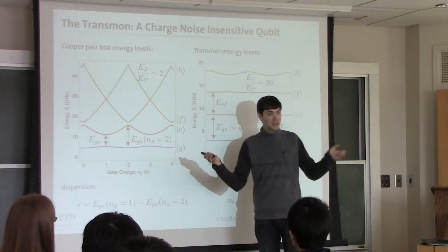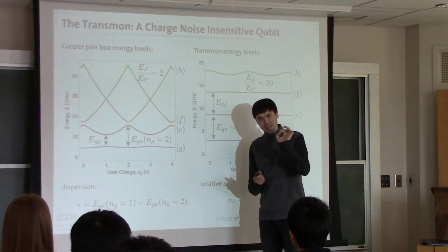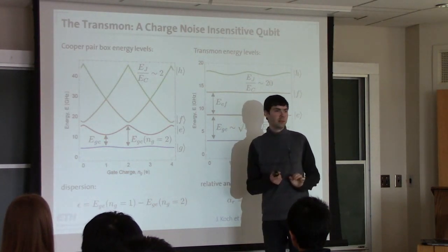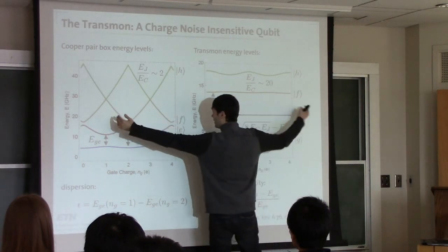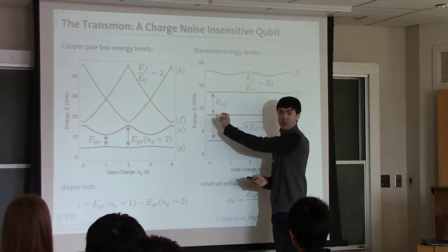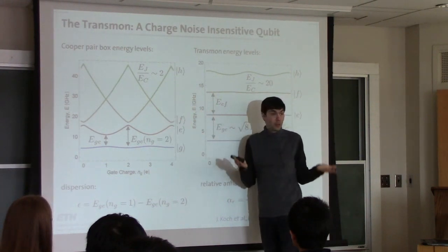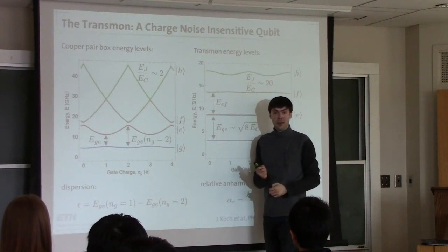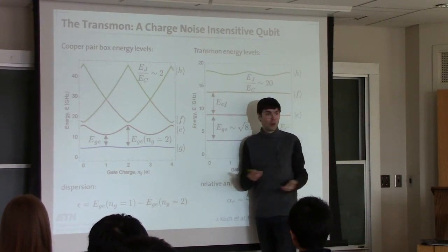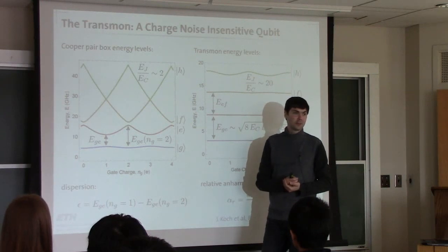It's a big capacitor with a tiny, tiny Josephson junction element that makes it slightly anharmonic. This is what it is physically. It's a capacitor this size with a little Josephson element. A capacitor is a completely understood linear circuit, and a tiny nonlinear element enables all the qubit work with these systems.